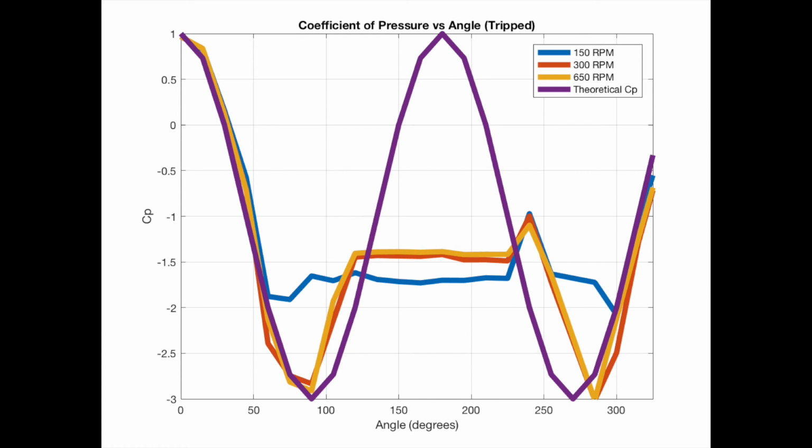This video also clearly reveals that the port corresponding to an offset of 240 degrees from the front of the cylinder gave bad data. The data here sharply dipped compared to the data from the ports near it, and this trend was present in all trials. Note that the pressure at 240 degrees was negative, so on polar plots, the pressure appears to coincide with an angle of 60 degrees. There are several possible explanations for this dent in the data.